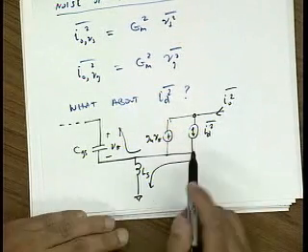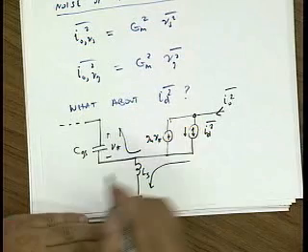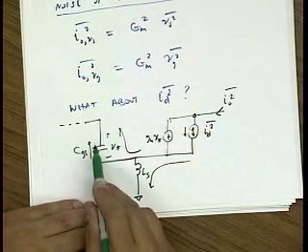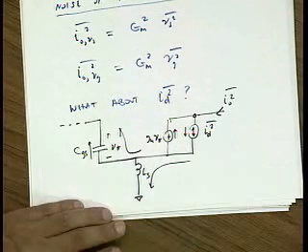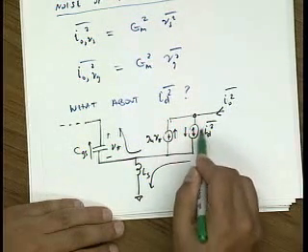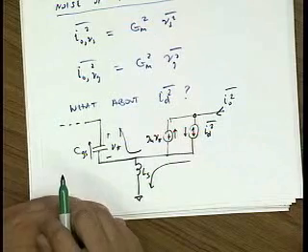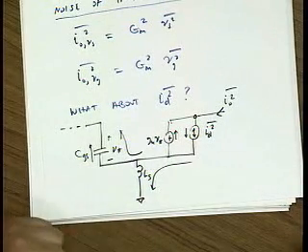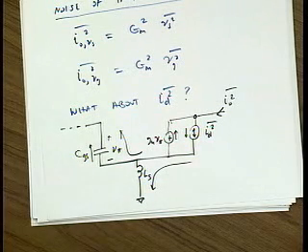But a little bit more careful thought shows that if we assume that initially this current is going down, and if that current flows here, it generates a negative VGS. And that would produce a current perhaps of opposite phase, which means that not the entire I drain will flow to the output. Some of it will actually flow into this GM generator. Okay? Questions or comments? Yes? Yeah, exactly. So if you've taken 240, you understand exactly what we're talking about.